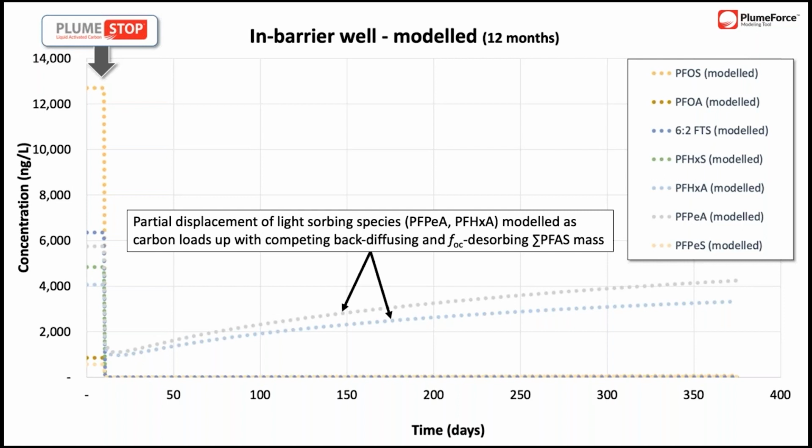And indeed, for perspective, the local drinking water standard for PFHxA is 400,000 nanograms per litre. And so from the get-go, we're less than 1% of this. PFPeA isn't listed in the regulatory drinking schedule either. So the model performance is therefore at compliance.